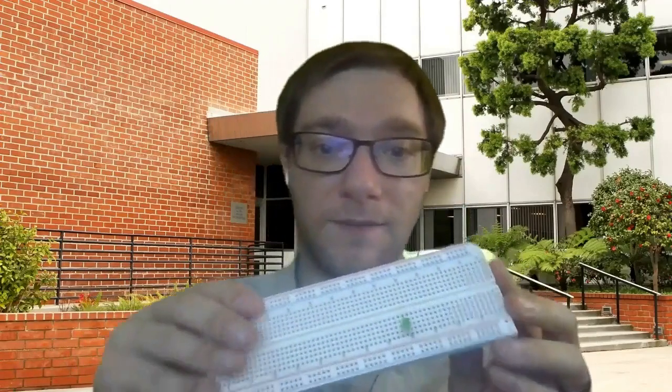The little legs themselves are very thin and bendable. And in order to plug things like this LED into your breadboard, you just press them in so that they stick like that. In the diagrams that I'll be providing you, you'll see that sometimes you need to bend the legs of a component like the LED a little bit so that they will be about 3 holes apart.